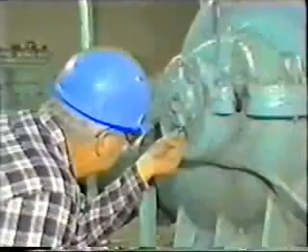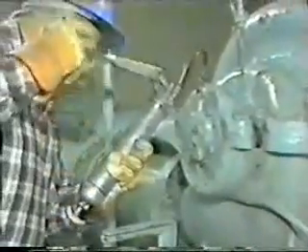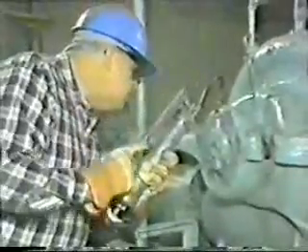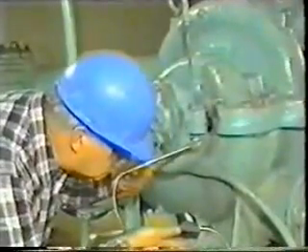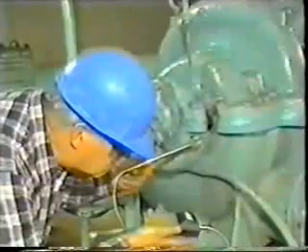He has checked for excessive grease, and earlier he checked to see whether the seal was leaking, but the problem could still be too little grease. To verify that there is too little grease, you can add grease in accordance with your facility procedures. Then, monitor the temperature to see if the temperature comes down. A temperature decrease would indicate that there probably had been too little grease on the bearing. So in this case, verifying the cause of the problem and fixing both the problem and the cause are the same thing.